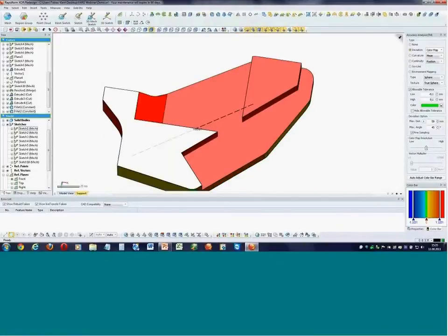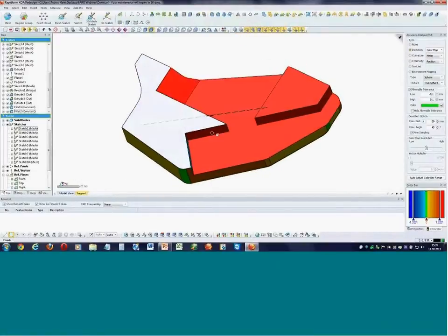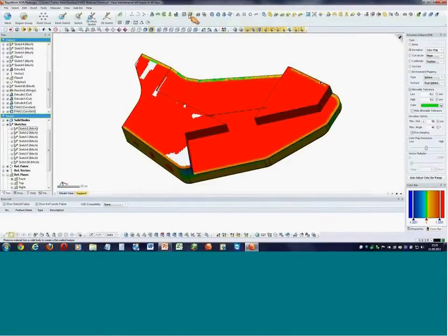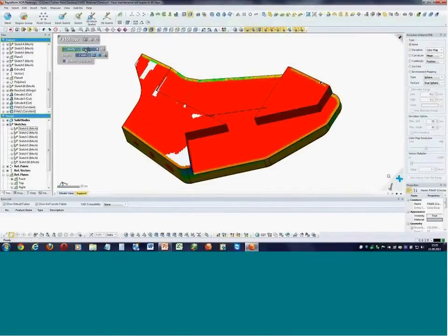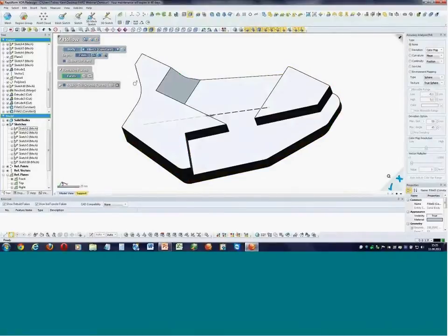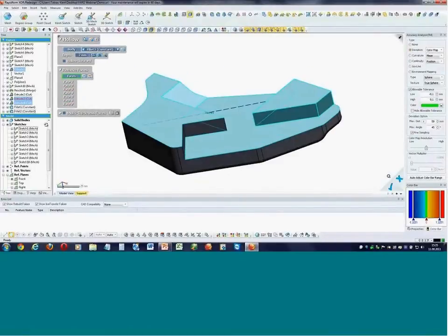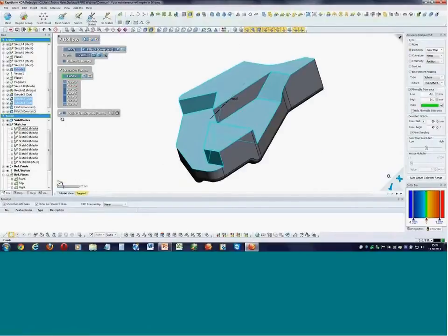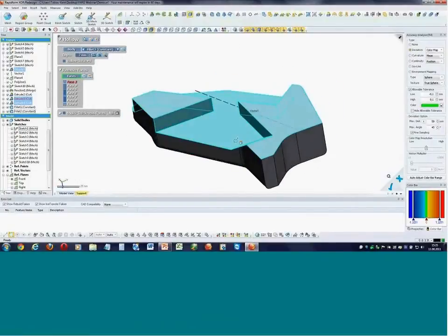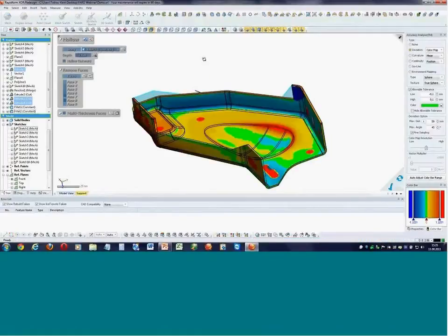we can make a sheet metal model using the hollow feature. We need to select the body and we need to select the wall thickness. Then we can remove some faces which should be not inside the sheet metal part. And then we will get the sheet metal part.